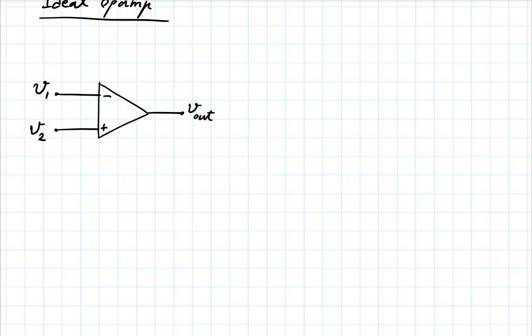That makes it possible to build a large number of circuits around them where the op-amp gain itself, as long as it's very large, has very little effect. So most things are determined by everything else around the op-amp, and that's why the ideal op-amp model is very useful, especially if you want to gain insight into how the circuit works and design things.